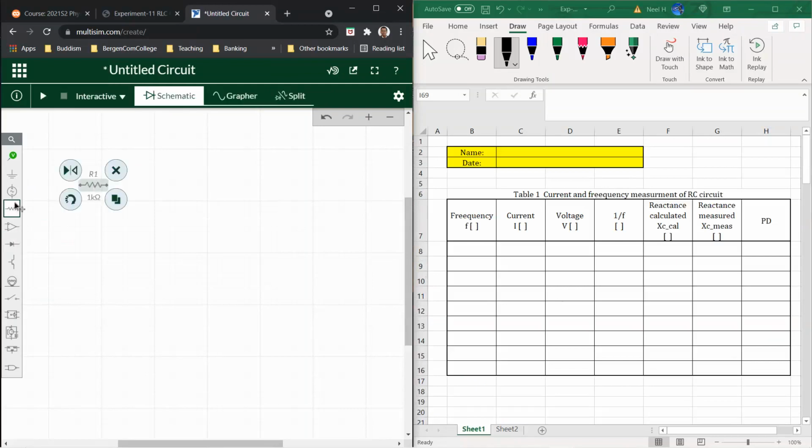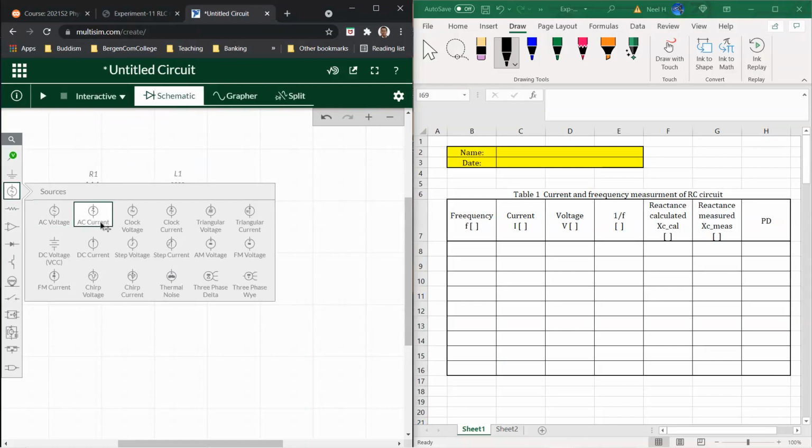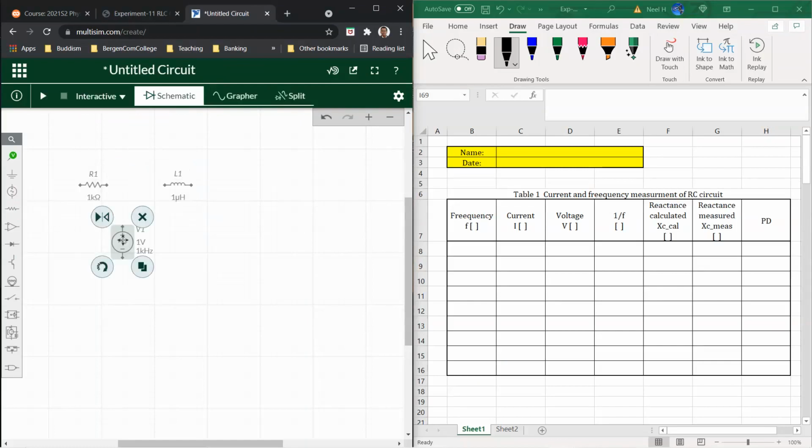Okay. So we need the resistor and we need the inductor. Just keep space between them to put the voltage sensor on. And then we need the AC voltage supply in this case. Usually I rotate the AC voltage supply with the negative to the right side because the negative side should be grounded. Otherwise we have to do a couple of other things. The grounding externally is actually the AC one. Then I need the switch.